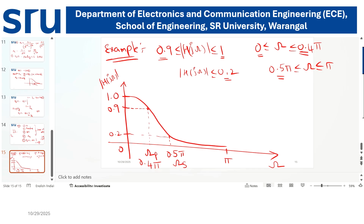So we have the passband frequency and stop band frequency, and always remember, if alpha p, that is 20 dB, and alpha s, that is 30 dB, are given directly, then you have to consider the first formula for finding the n value. Now here we are given a characteristics specification.